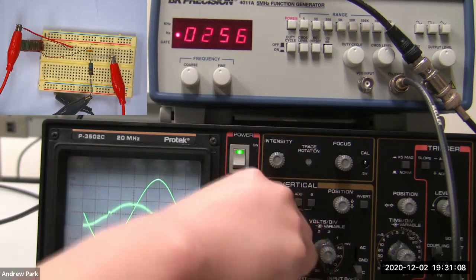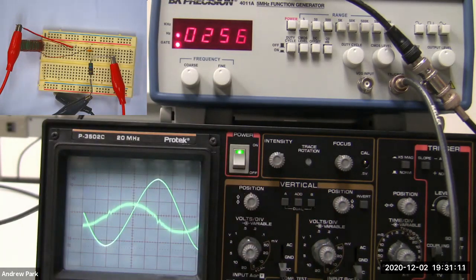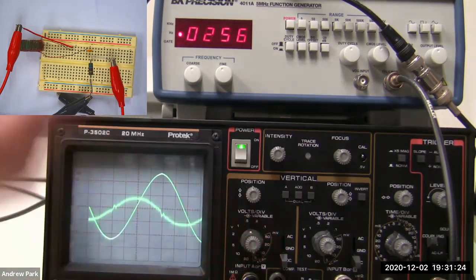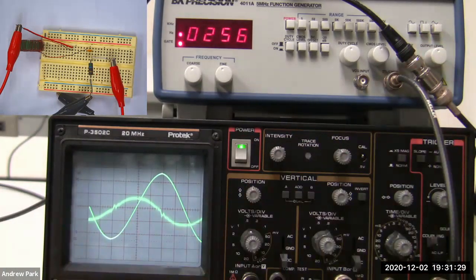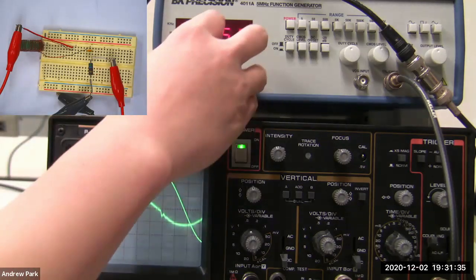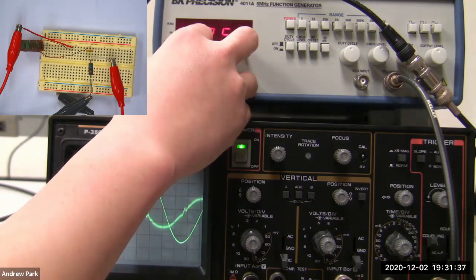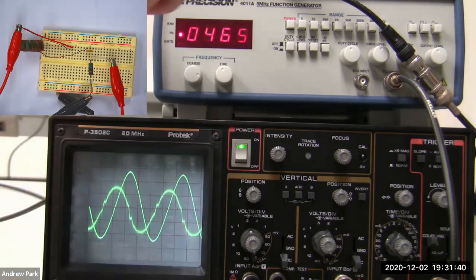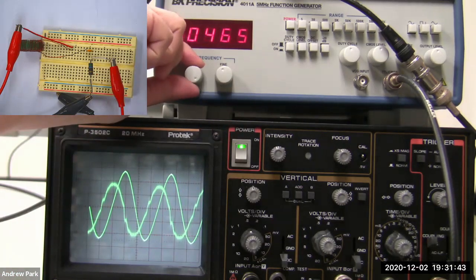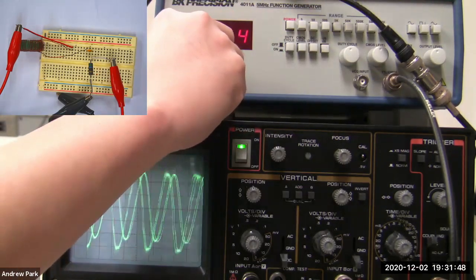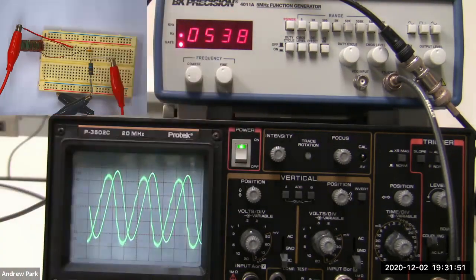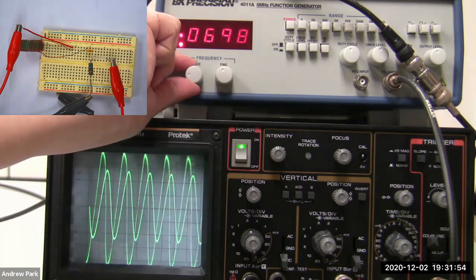So yeah, and the output, the current that's going through the circuit, I do have something there, but it's very, very tiny. This channel 1 is right now on the smallest scale. I think that's 5 millivolts per division. So I think the resonance frequency was at the higher end. So as I increase the frequency, what you see is that the current amplitude is going up. Oh, wait, I reached my limit there. Let me go to the other one. And let me start at around 500 hertz. Okay. So as I increase the frequency, the current is increasing.